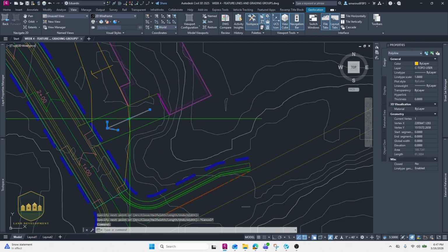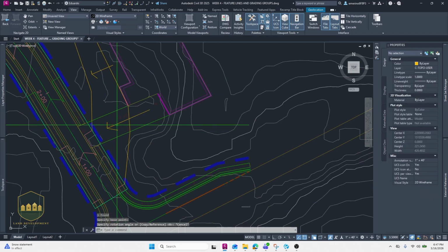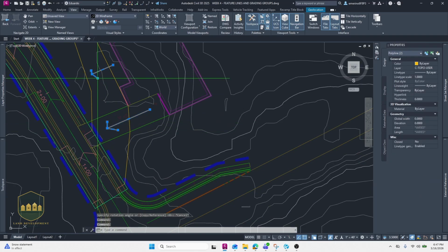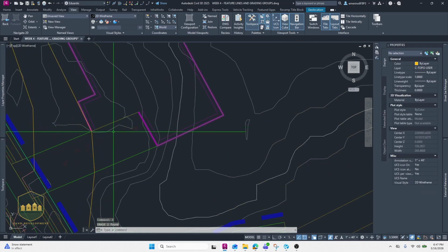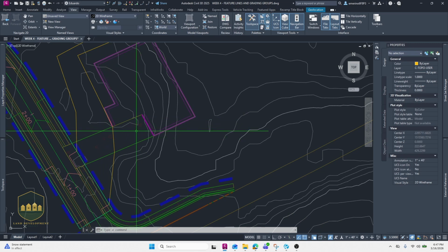I don't want water draining this way. Even though you'll see a lot of houses designed that way, those houses have stormwater management systems that capture the water before it hits the garage. But even if those, let's say, structures fail or they're filled up and the storm is massive, I mean, it can lead to flooding to the house, so it's best to avoid it.